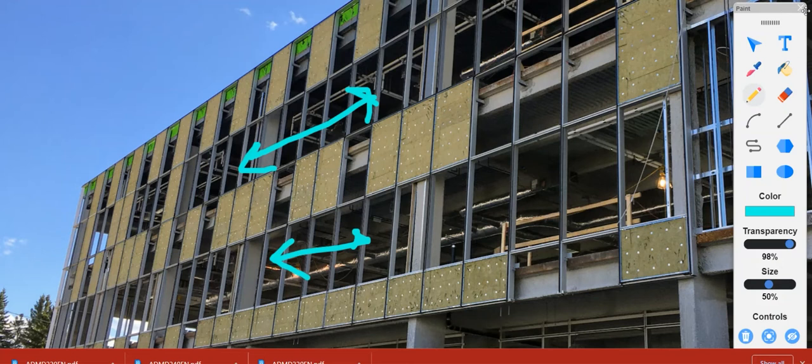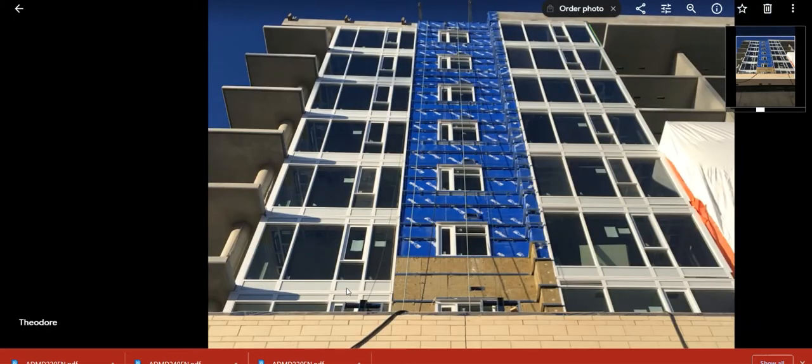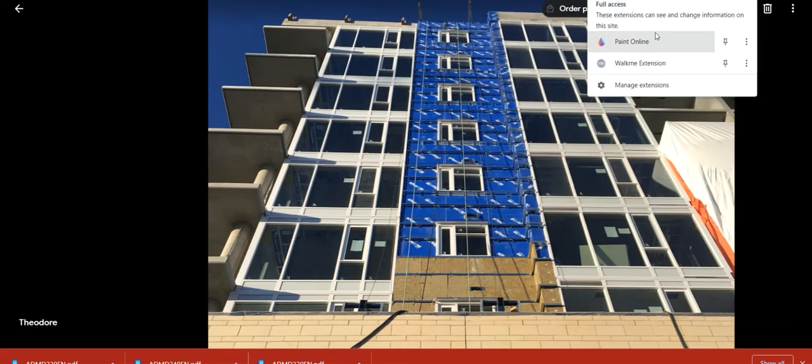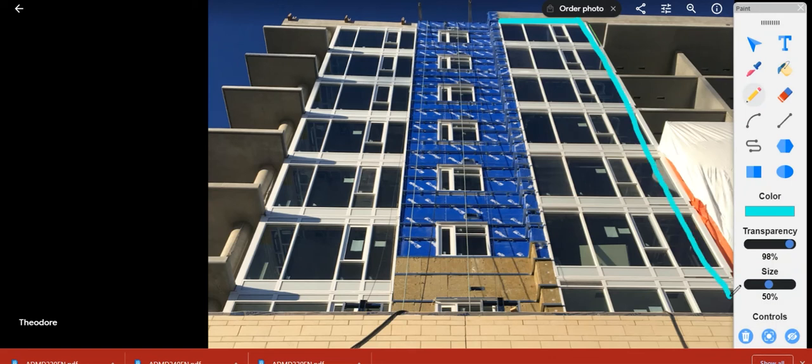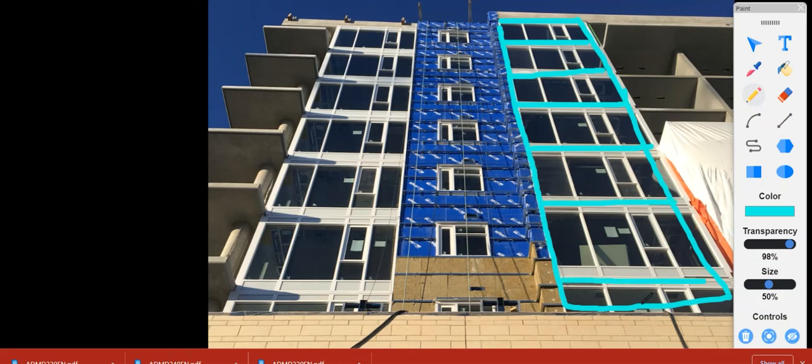So the window wall system looks like a curtain wall system. So it looks like you have a full glazed panel system on this building. Okay, so right here, which you do, but it's not actually hanging off the structure. There's actually panels on each floor that is spanning between the floor structure. So in this case, what do we got here? It looks like there's 1, 2, 3, 4, 5, 6, 7 essentially separate panels there. And again, they're framing between the floor structures.